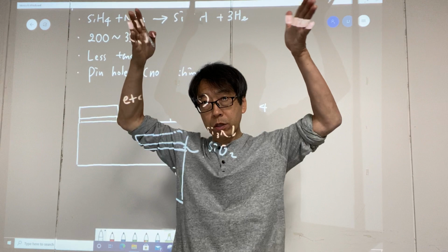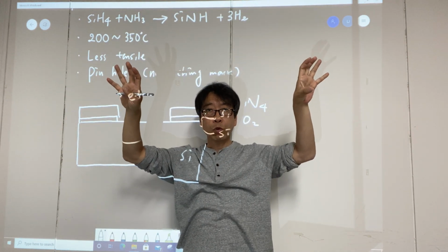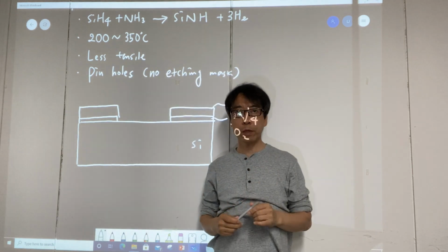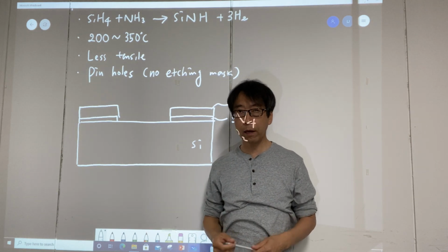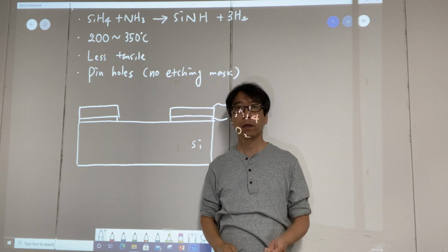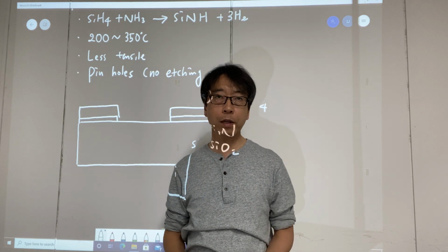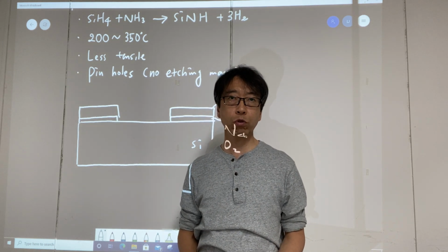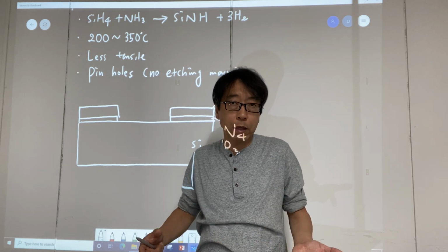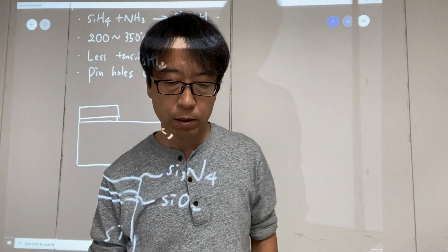And then just by using a lithography process, you can pattern photoresist on top of it, open the window, and then use some specific chemicals that I'm going to go through later on to etch such a window away. This could be chemical, this could be plasma, this could be gases, many different kinds of etchant can be used to define or open up such a window. That's what we did. So the whole process is compatible. You can align the whole process.